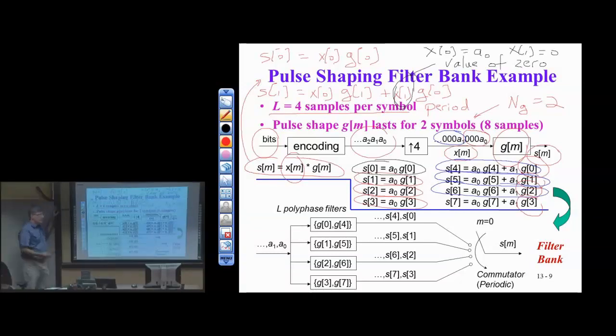So now if I want to design a signal processing structure to do this efficiently, I can do it through a filter bank. Now normally you would think, gee, it's a filter bank, it should take more operations. And yes, that's often the case. But for this case, it's going to take fewer operations because we've tailored the filter bank structure to remove the multiply by zeros. We just don't do them. So it becomes actually more efficient.